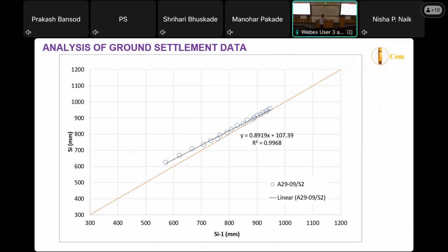But the important thing is that you have to put all the readings at the same time interval, the same delta time duration. If you put readings for every day, then every day. If you put every week, then every week. You cannot change it. Once you put yesterday's, you cannot then jump after 7 days; never do that. You have to be uniform. The duration should be uniform, depending on the settlements you are plotting in these graphs.